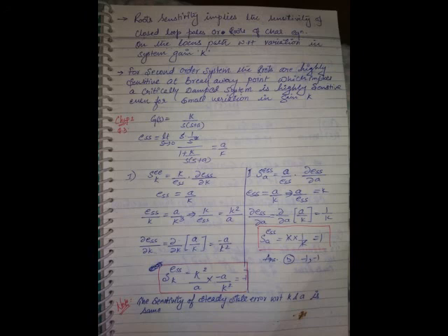These are the disturbances. So one way to eliminate the effect of disturbances is to use controllers here. We have seen just now that PI, PD, PID controllers are used to eliminate the effects of disturbances, that is, to eliminate this error which is occurring due to disturbance.